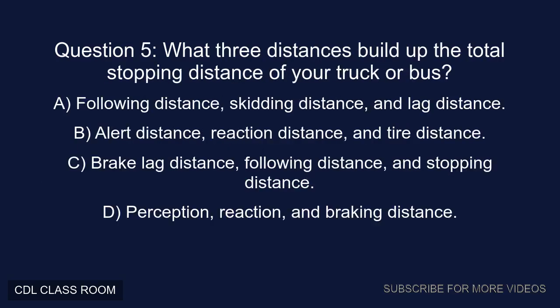Question 5. What three distances build up the total stopping distance of your truck or bus? A. Following distance, skidding distance, and lag distance. B. Alert distance, reaction distance, and tire distance. C. Brake lag distance, following distance, and stopping distance. D. Perception, reaction, and braking distance. Correct answer, D. Perception, reaction, and braking distance.